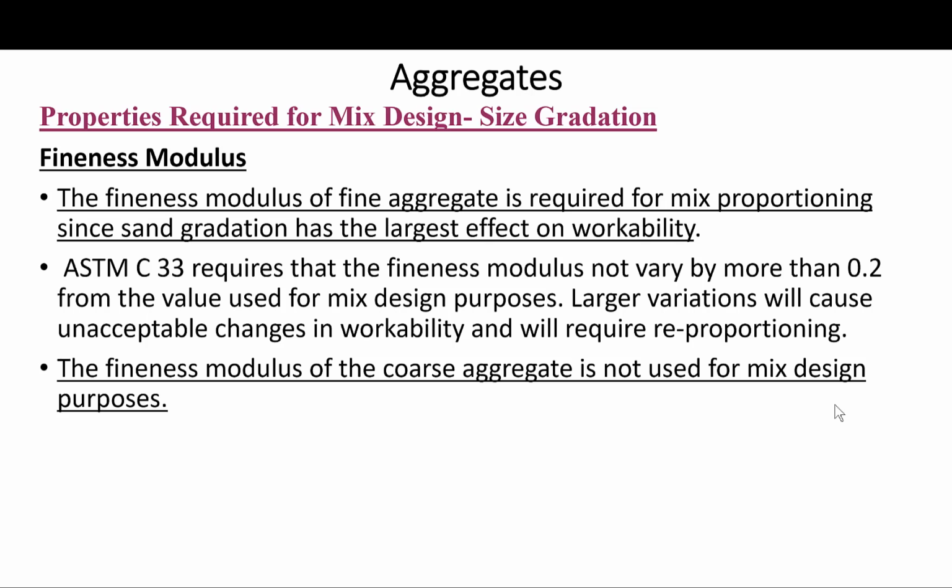Okay, so you base your calculations on a certain fineness modulus from a certain grading of aggregates, and that's what you base your mix design upon. If the value varies by more than 0.2 as indicated, there will be some recalculations. As I said, the fineness modulus of coarse aggregate is not used for mix design purposes. Okay.